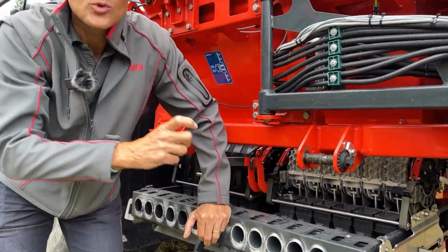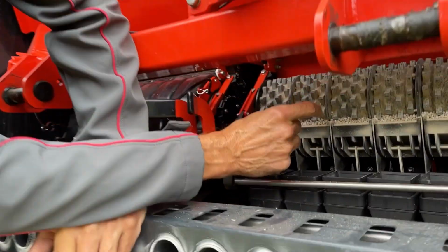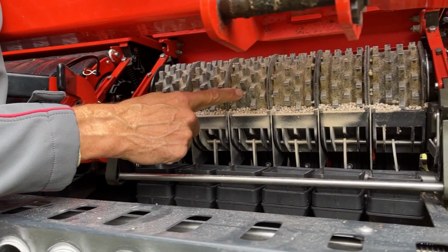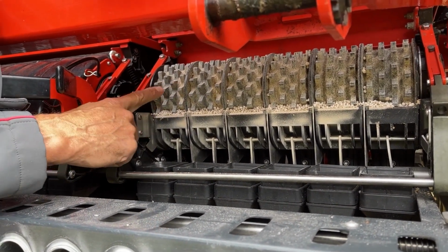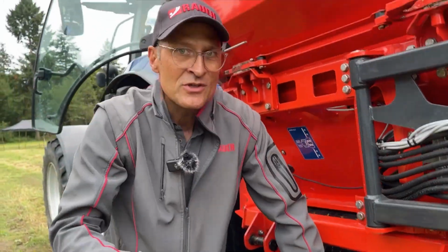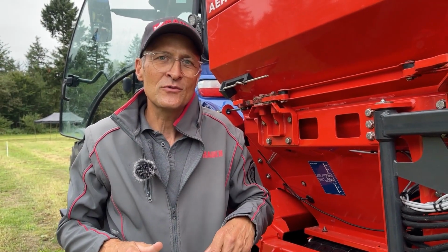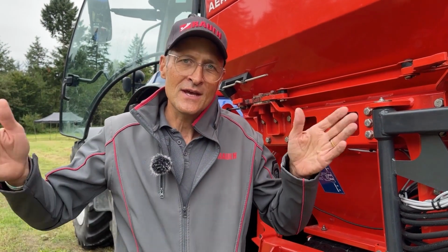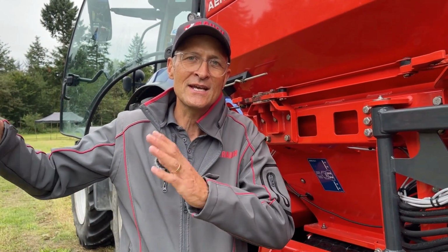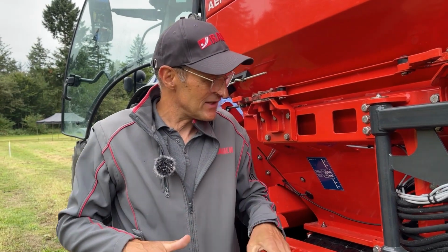And now we have a split dosing roller, so we can drive each segment individually, which means that each segment has its own speed, determining the amount, and we can also switch them on and off. So for section control, for example, depending on the working width, in 1.20 meter steps, we can adjust the sections. So the spreader has, for example, 20 sections or 24, depending on the working width. The larger ones have 24 sections, 20 and 18 are for the 21 meter model, and then each section can be switched on and off.